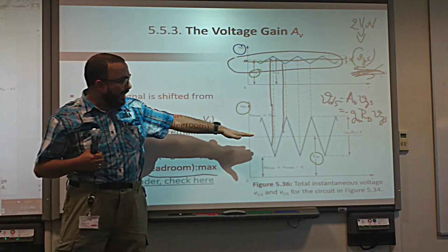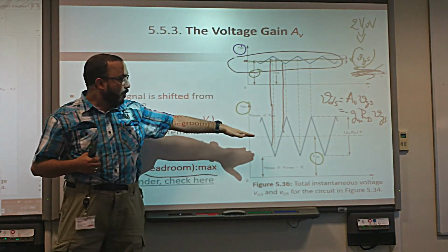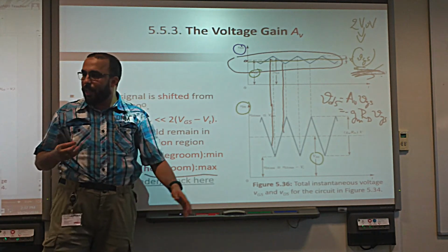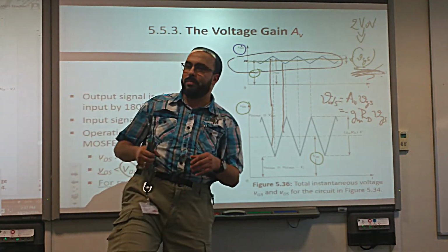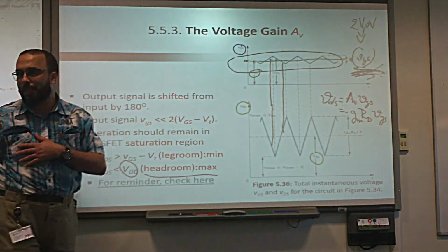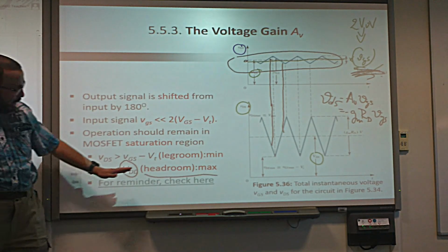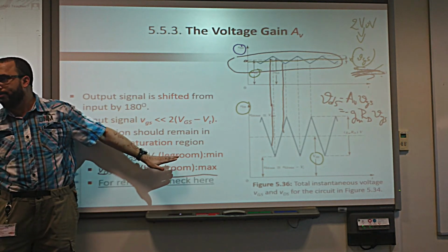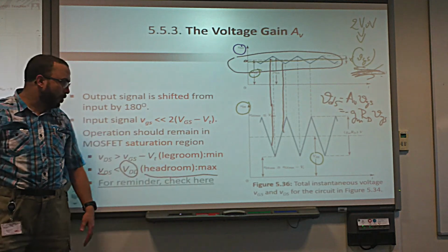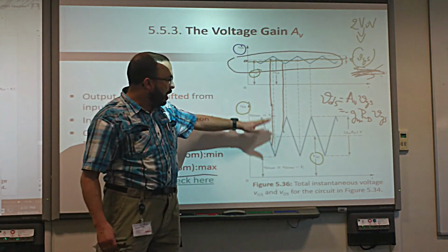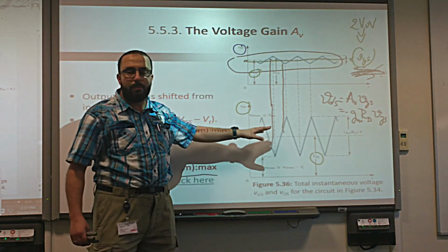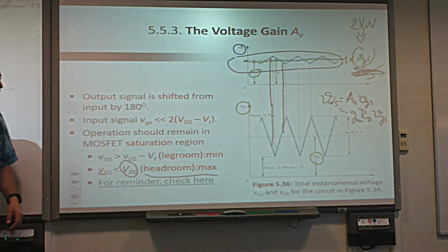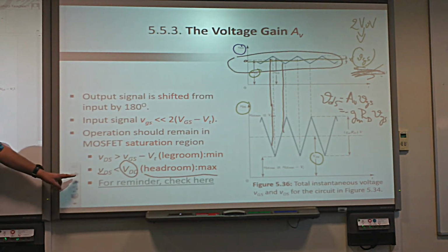So it means that the signal cannot jump up too much. If we make VDD higher, that means we have higher headroom. Now, for the same thing, some cars have enough what? Leg room. It means you can put your leg and sleep. This is also leg room, meaning the minimum value of VDS can go down, but it cannot go below V overdrive. Do you understand? That's what we mean. So now my signal can jump between these two, but outside these two, we don't have anything. The amplifier is not working. See how important this is? Very good.